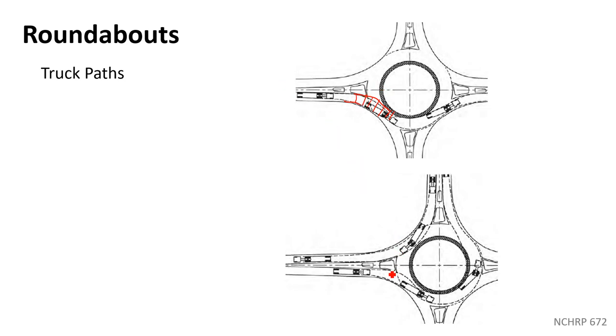Maybe down here is easier to see now because I drew all over the other one. Look how close that is to the edges, right? So part of the reason for that flare is it does let trucks get through there easily, and it's keeping off the curbed island. And this outside is quite often curbed as well. So we're keeping the truck off those curbs on either side, which is a good thing. That's what we want to do through there. You can see his front tires. They have to really, whoops, it doesn't like when I push down too hard.